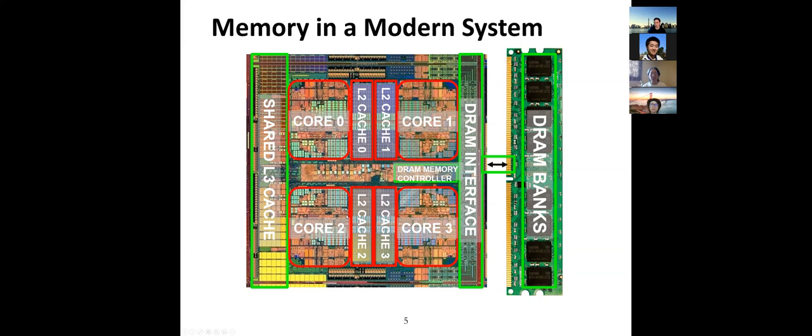Obviously, there is also the memory itself that's important. So here you're going to see the pins for the DRAM interface, right? And this is the DRAM bank that is actually off chip. Those are the pins that connect it with the core, with the SoC here. And this is the DIMM, right? So you see memory is outside.